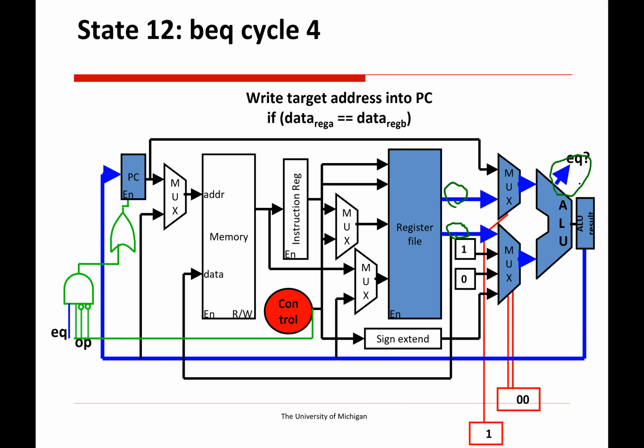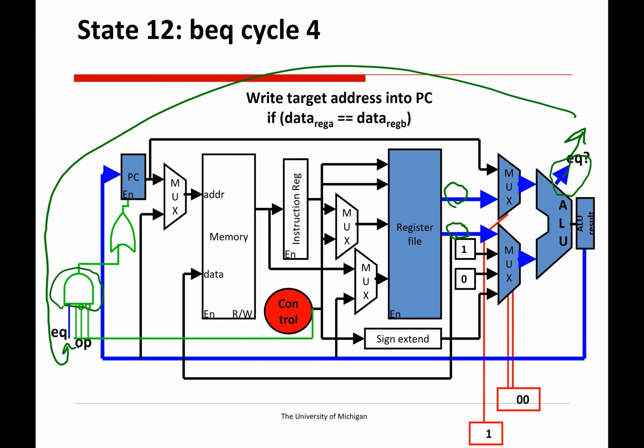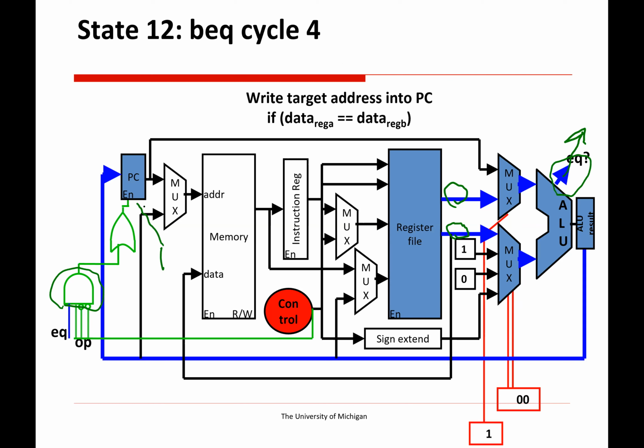But then we saw we have this extra control logic over here. This AND gate is checking to see if this is a branch instruction and if this equal output is true. So if that's true, then we'll enable this PC. But remember that before, we often had a hard-coded value going into this PC enable. I still want to be able to do that. I want to say if the decoder is outputting a 1, that we should ignore this logic.